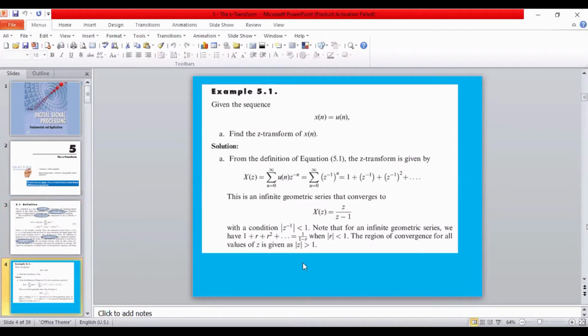And here's the example. For instance, imagine our input signal is a unit step, a familiar test signal. It is 0 up to time 0, and then when n is equal to 0, it jumps to 1 and stays there. Just as we call it, unit step, right? We need to find the Z transform of this input signal. Okay, so it's quite a simple solution.